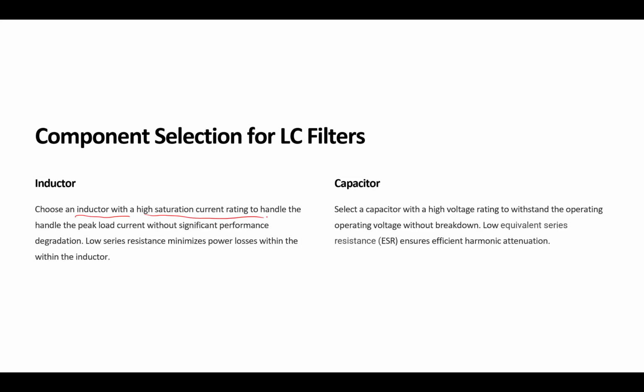Very good. And it has a low resistance, because in practice, the inductor is a conductor wrapped around a certain core. Any conductor has a resistance, so it's not just an L. There is an R in it.